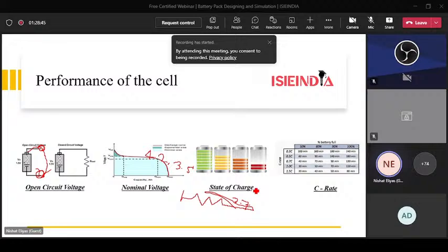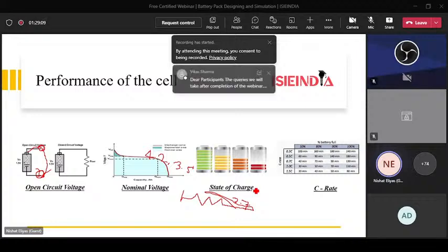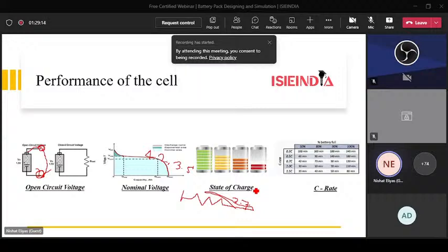When for the 0 second you check the voltage with the multimeter, you find the voltage is like 4 volt. For the next 1 second you get 4.3. Then again for the next second the display on the multimeter shows 3.6, like 3.5. Then again it comes to a constant voltage where it is showing like 3.7. And for a longer time it remains constant with a little bit of fluctuation in between.